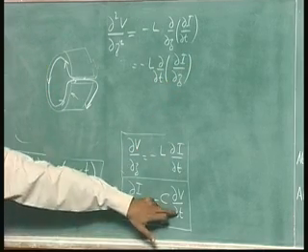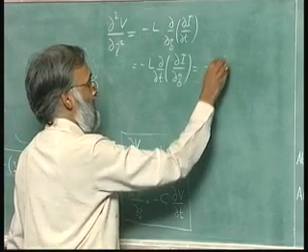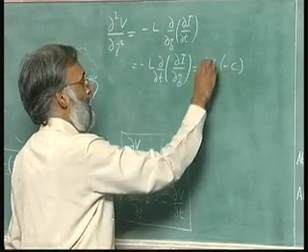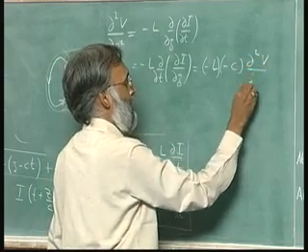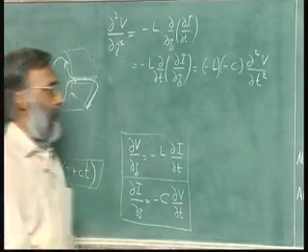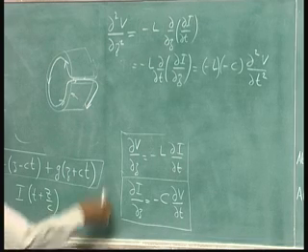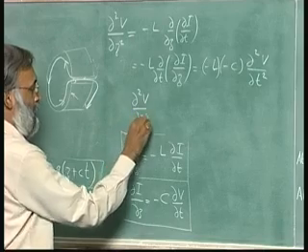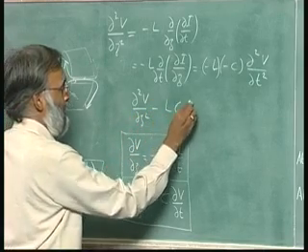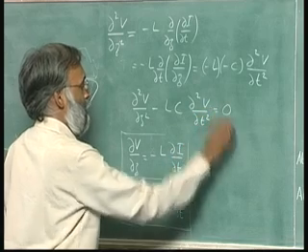Apply this equation, I get minus L times minus C times del squared V del T squared. So we get the final transmission line equation, which is del squared V del Z squared minus LC del squared V del T squared is equal to 0.